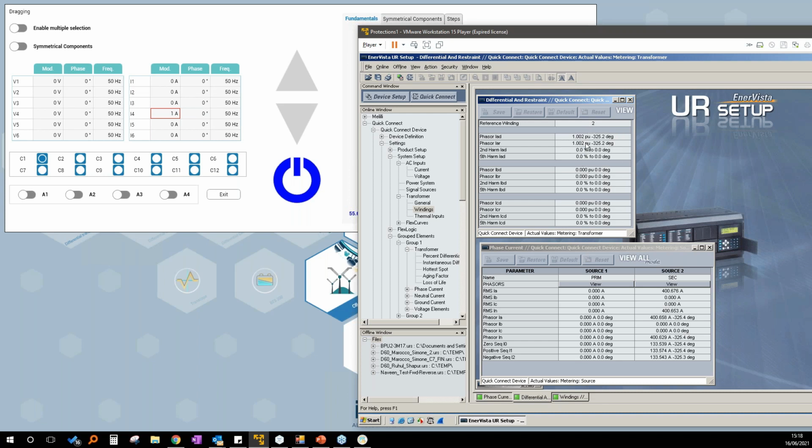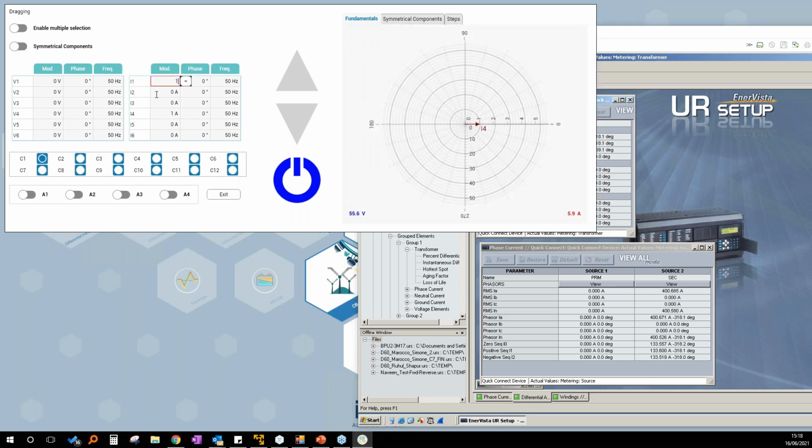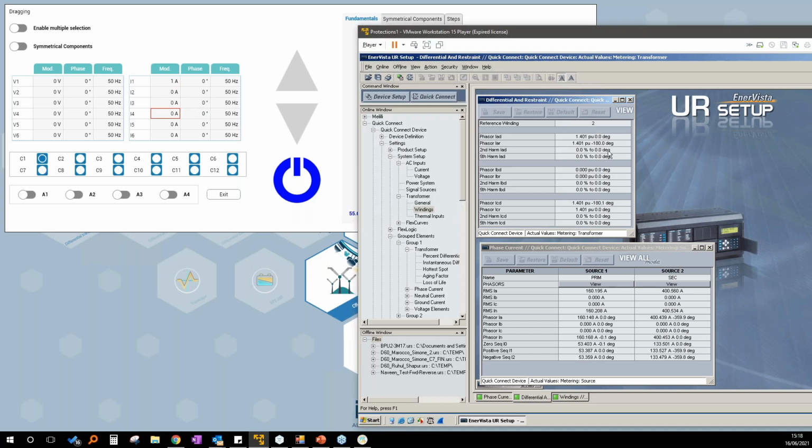I repeat once again, because for all the currents generated into the low voltage side, the matrix used is the unit matrix. But going back to the current into the high voltage side, where the compensation is present, I want to prove that there is the possibility in the relay to disable this compensation.